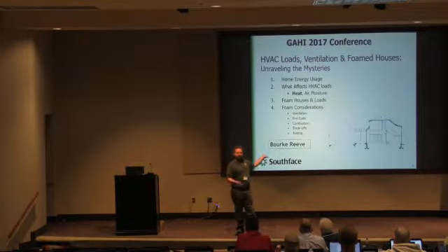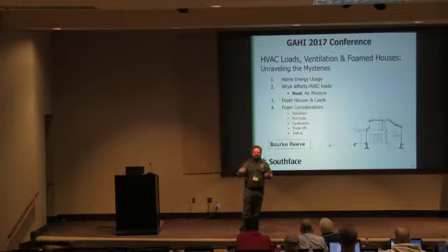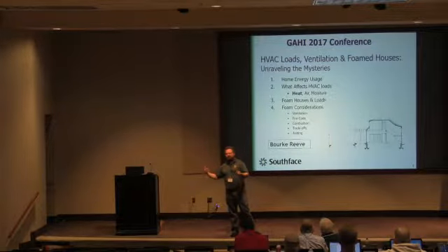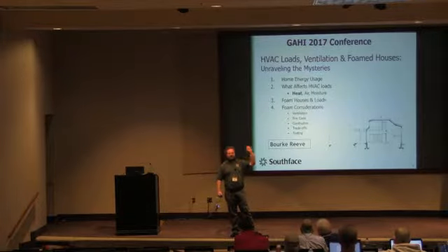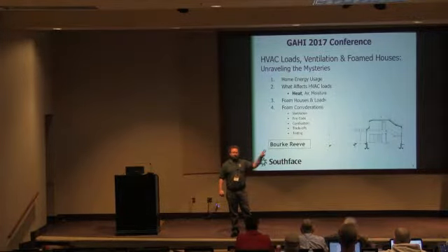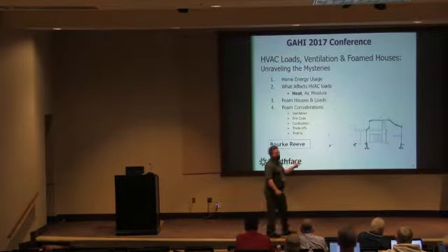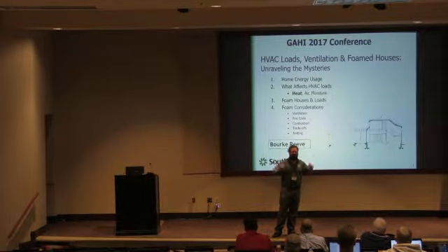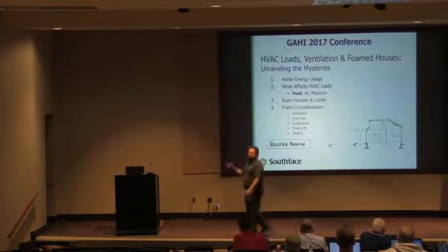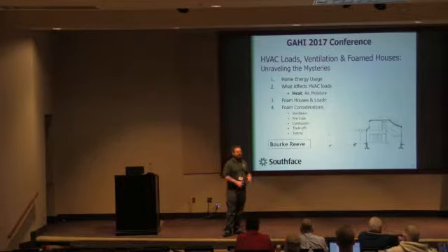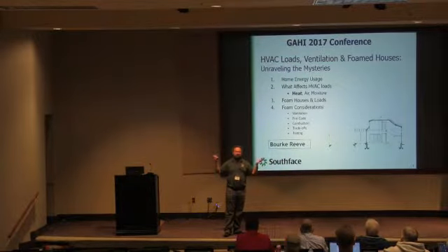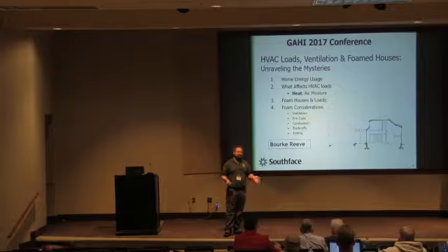It's a common retrofit in an existing home, and as I'll talk about, it's also stuff that we're starting to see coming into the energy code and the residential building code, the IRC. We are moving to a future where houses have to be tight and have mechanical ventilation, not uncontrolled air changes. We used to look at a spray foam house and say, well, that's an unusually tight home, so we have to think about combustion safety and ventilation air. The energy code and the building code have pushed us to a point where all new homes are tight homes, and all new homes are going to have to think about ventilation and combustion safety.